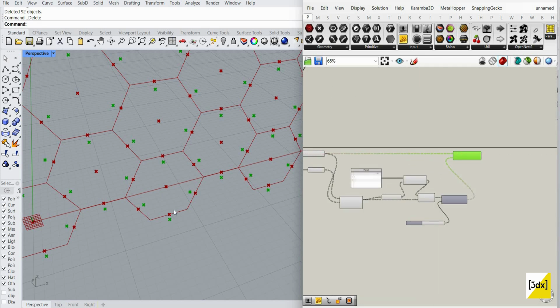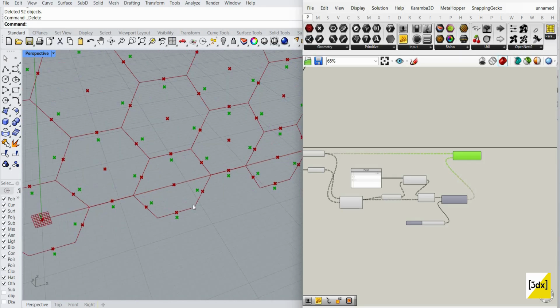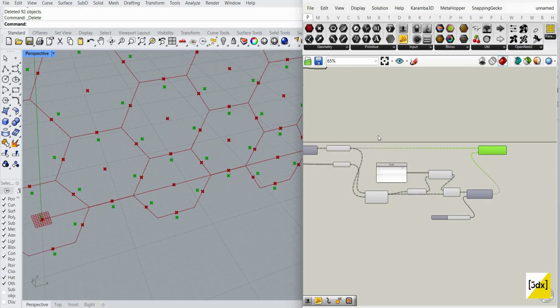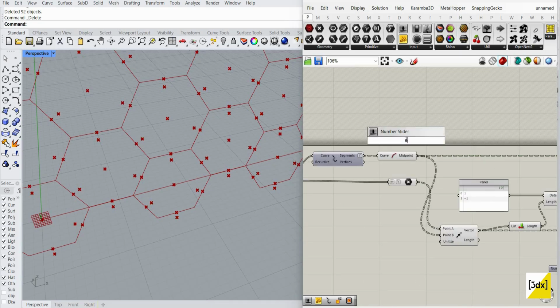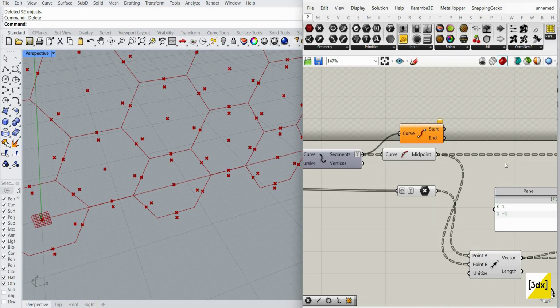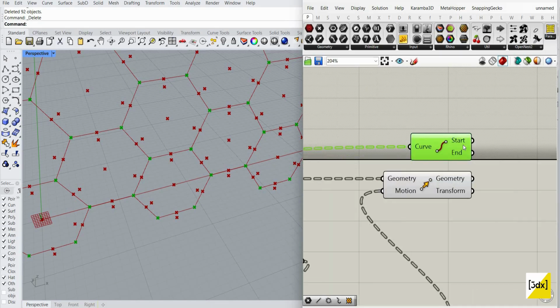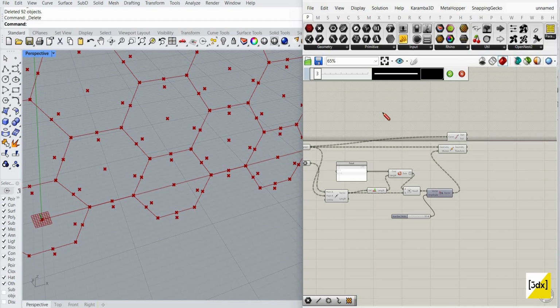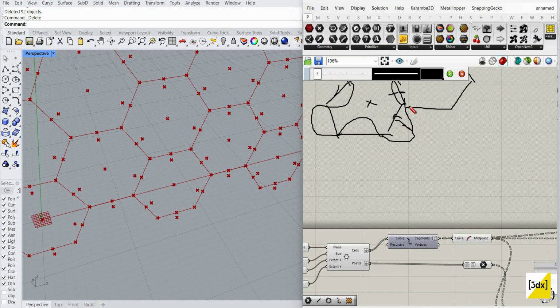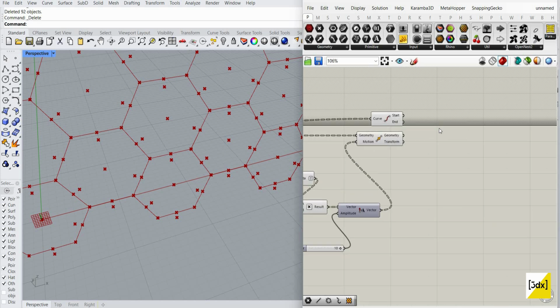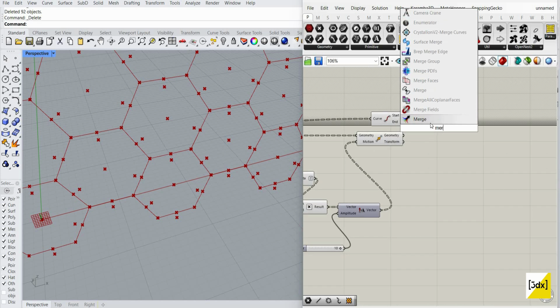So now you have some points, but I need to create an arc. Let's say I'm going to take the endpoints from the segment. You can see everything is selected. I'm going to take the endpoints and middle points, so I'm going to create a list with 3 points: start, middle, and end. The middle I'm moving. So how can I create it? I'm going to merge it.